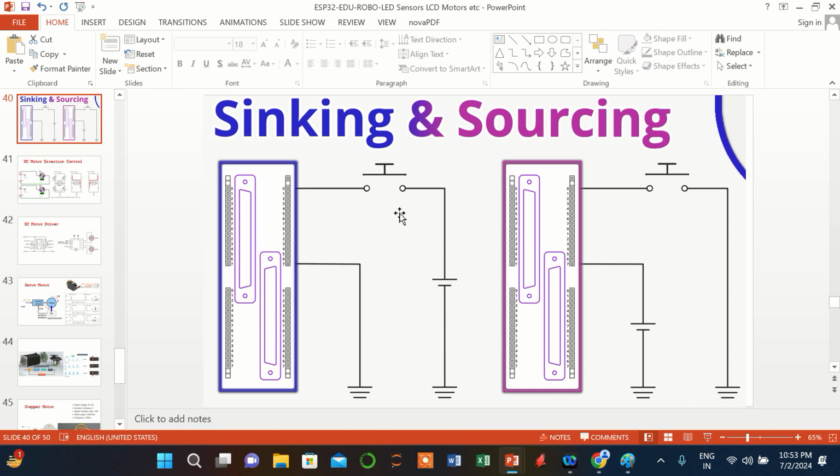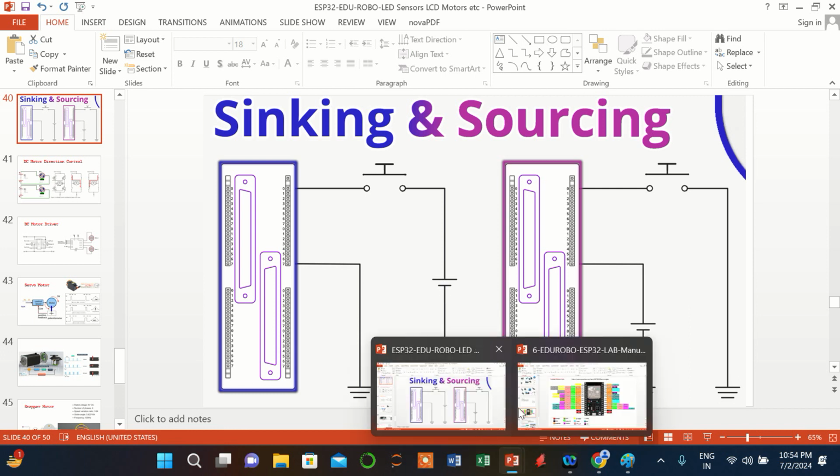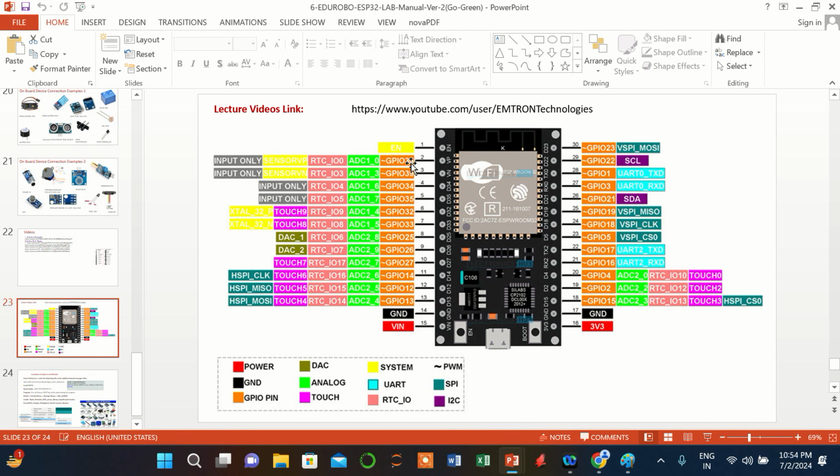So please understand, in electronics, load means not voltage. Load means current. The amount of current that will flow. Alright, so as the VCC increases, also increase the resistor value so that the current remains the same. So this is the precaution you should take. Alright, so with this brief introduction, now let's interface various sensors to the microcontroller pins.